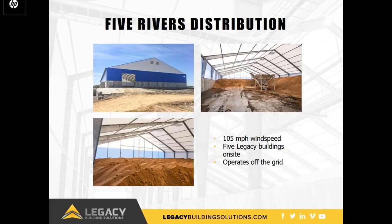But of course, not all winds are hurricanes. Mountains and other open areas are also known for exposure to strong winds, and the wind exposure should be calculated as part of the building design. This building is along the Arkansas River and is engineered for wind speeds of 105 miles per hour.